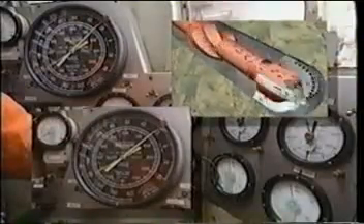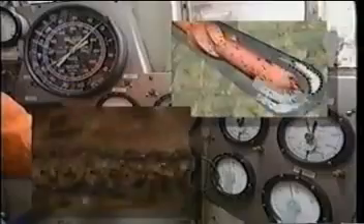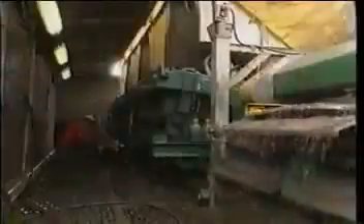An essential element of high-angle hole cleaning that needs to be understood is the fact that if cuttings are flowing over the shale shakers, the hole is being cleaned. The question now becomes, how fast are we cleaning the hole? Are we generating cuttings into the wellbore faster than we're getting them out? And is there a way that we can measure this? The first step towards answering these questions is to define the elements that affect efficient hole cleaning.